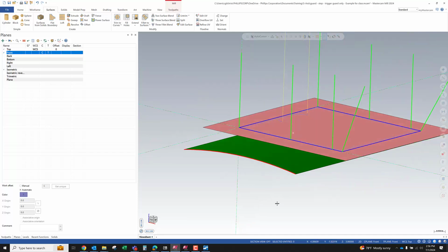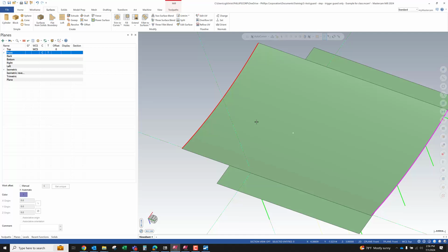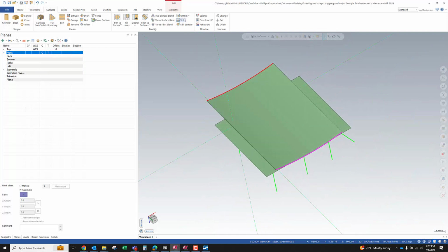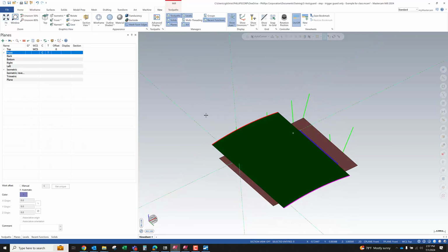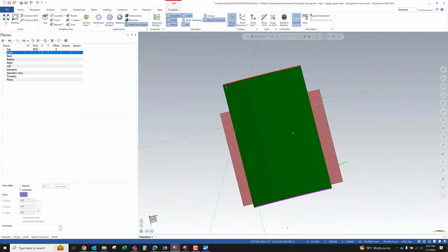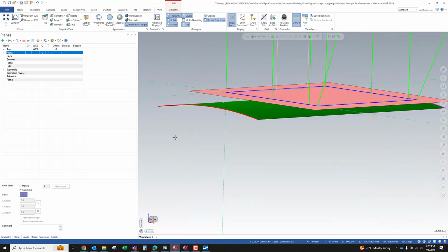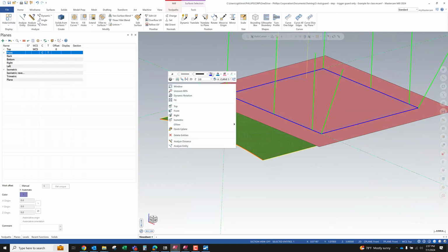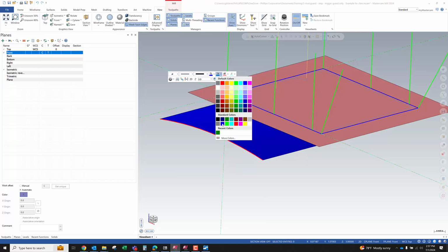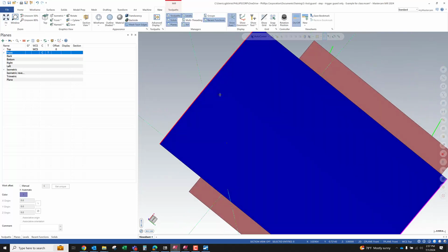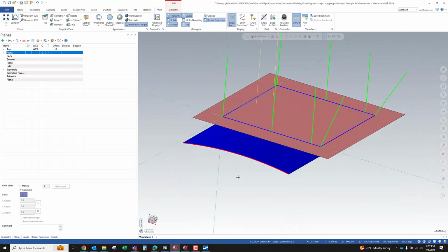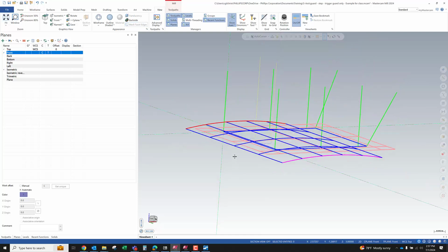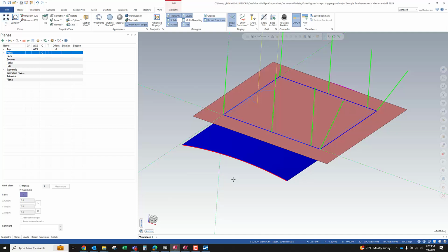Change this to a green. So there's a setting in Mastercam under the View menu, the View ribbon, called Backside. Now, when Backside is not enabled, the top and bottom of every surface are going to have the same color. Whatever color the surface itself is set to, it's going to appear as if the surface has the same color on both sides. And I believe that's true, yeah, even in wireframe display mode.